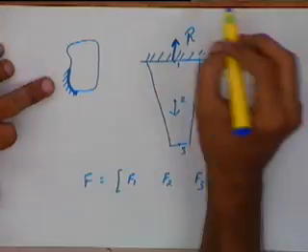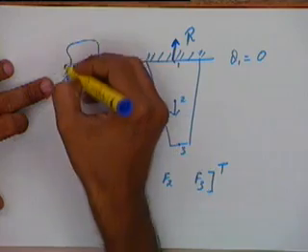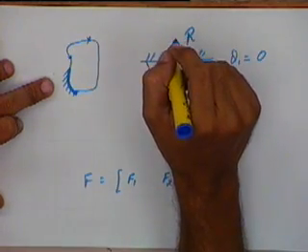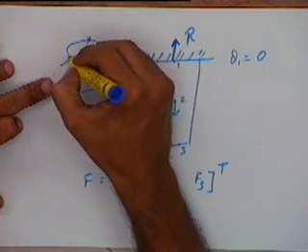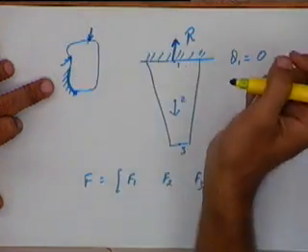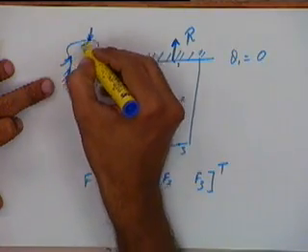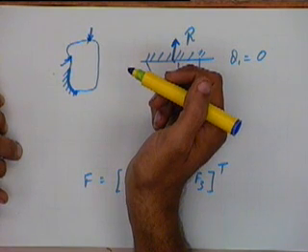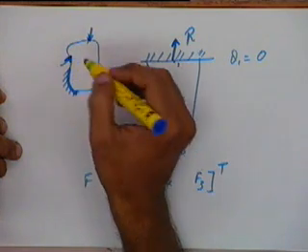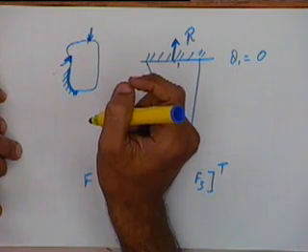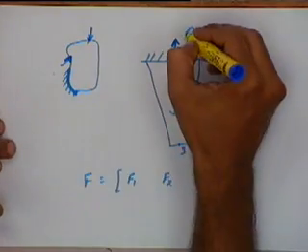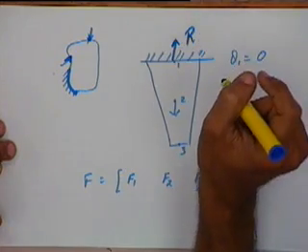Similarly, when you are talking of multi-point boundary conditions, with some node here and some node here constrained together, it is possible that there will be some reactions at these 2 points, as a result of which the deformation of these 2 nodes will be constrained in some manner. We haven't yet seen any way of finding the value of these reactions. So let us see how we evaluate these reactions.